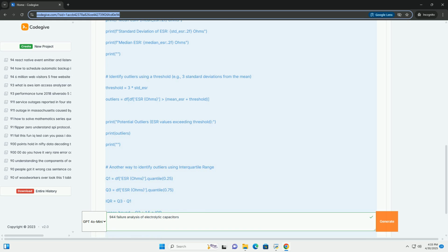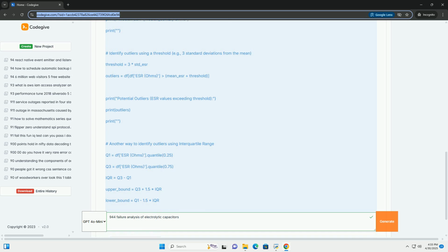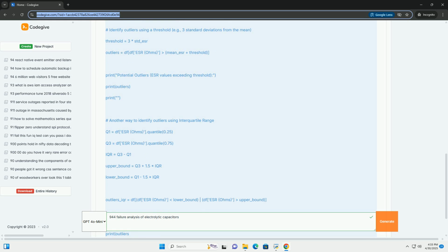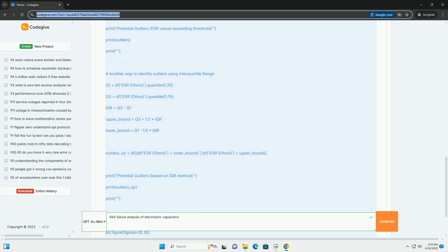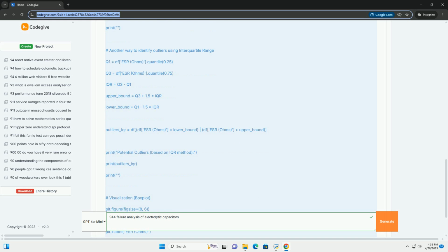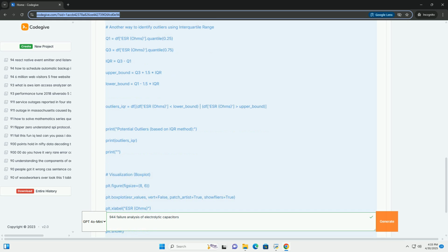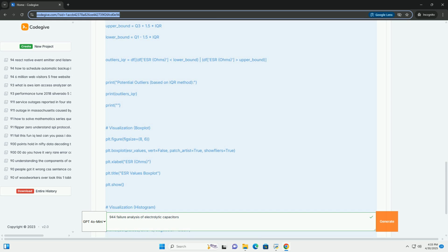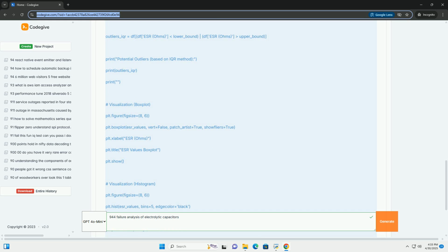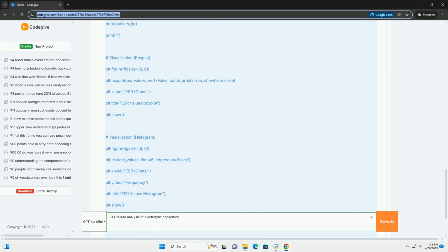Electrolytic capacitors, particularly aluminum electrolytics, are polarized capacitors that utilize an electrolyte as one of their electrodes to achieve high capacitance values within a relatively small physical volume. They are widely used for power supply filtering, smoothing, and decoupling due to their cost-effectiveness and energy storage capacity.